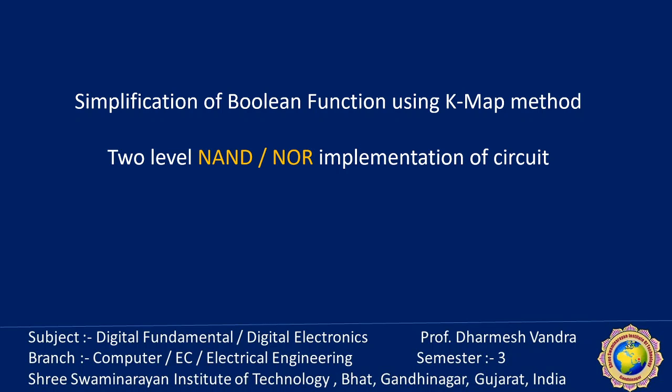Because of the prominence of the NAND and NOR gates in the design of digital circuits, rules and procedures have been developed for the conversion from Boolean function given in terms of AND, OR and NOT into equivalent NAND and NOR logic diagrams. This means we can implement any function with the help of NAND and NOR gates. So NAND and NOR gates are also known as universal gates.